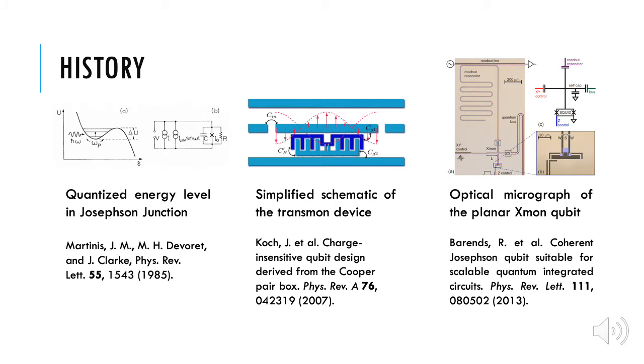In 1985, J.M. Martinis described quantized energy levels for microscopic variables based on current Josephson junction, and the position of the energy levels agreed with quantum mechanical calculation. From then, lots of research has been done in superconducting qubits field, and large-scale superconducting quantum systems become more and more practical from engineering point of view. However, there are still some effects that may demolish quantum coherence in superconducting circuits, such as material defects, electron system excitations, and radiative coupling to external wiring.